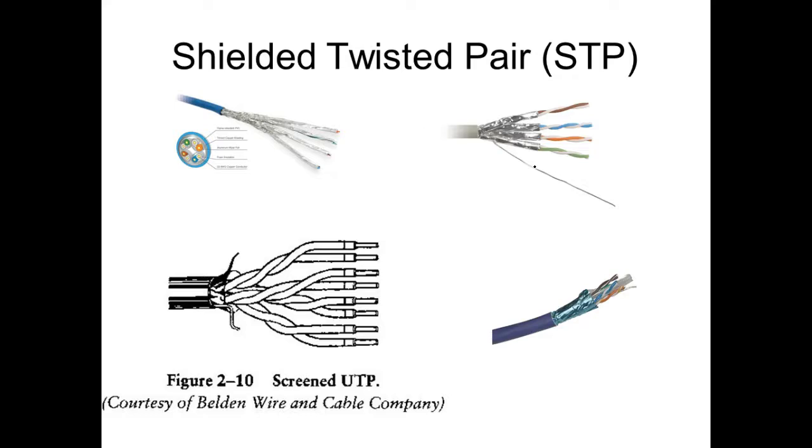So if we went over to that HMI panel, it's an industrial panel. They don't use capacitive. They use resistive. So you have to literally do what? You have to press that. What can you do with this guy? You just slide your hand across it, because what you're doing is setting up a capacitor. So I'm receiving 60 cycles right now, and if I can set up a way to sense that here, then I can do what? I can use the touch screen.